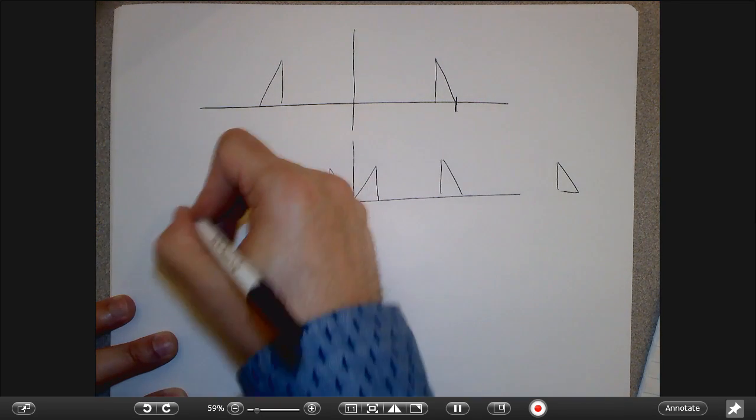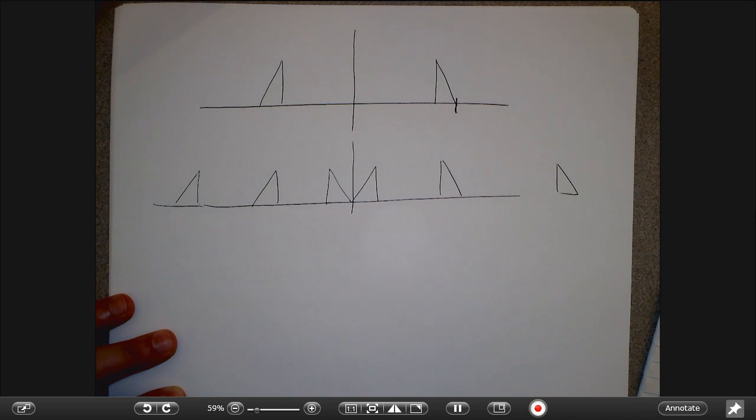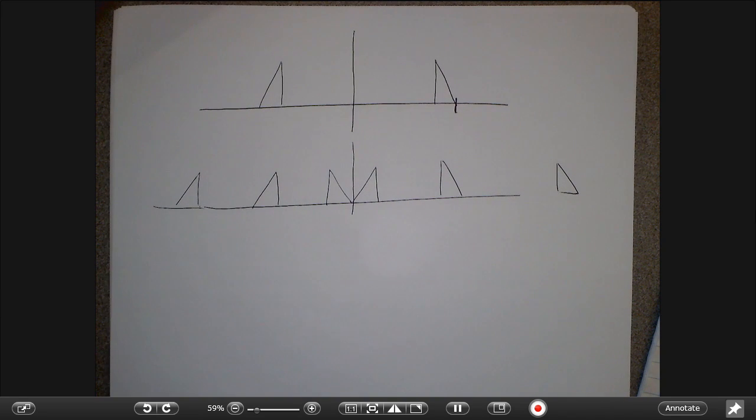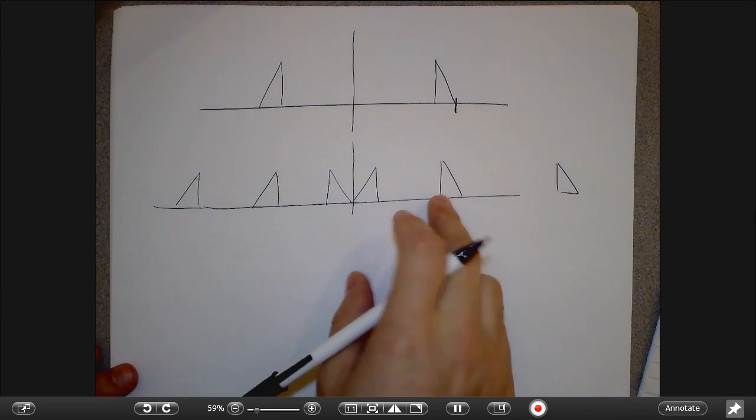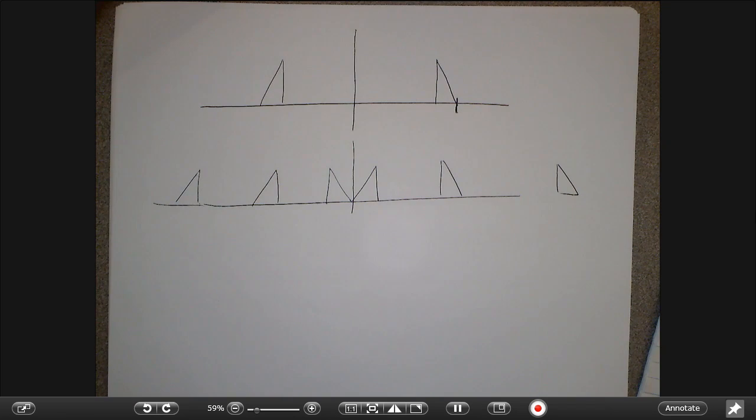So there's a way for band-limited signals where I can sample at a rate that is lower, possibly much lower than the Nyquist rate, but avoid copies in the frequency domain. And if I knew that that was the characteristic of the original signal, then I could certainly design things that would sample at a lower rate, but be able to reconstruct the original signal ideally.